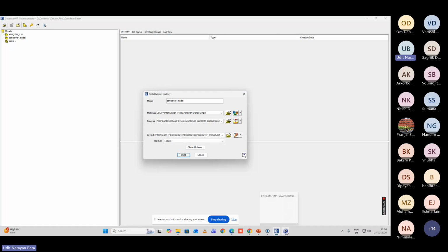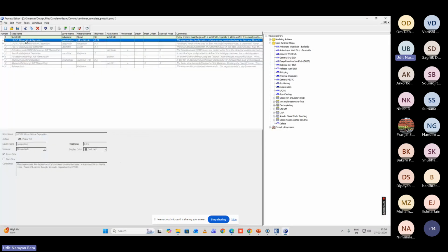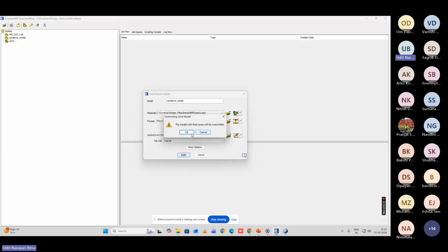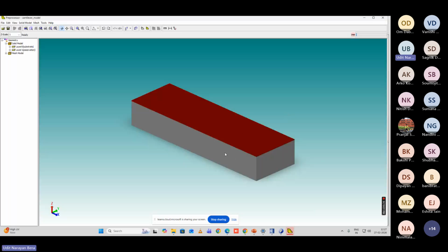Now, in the second step, what I'm going to do is add what is called a passivation layer, because we need this passivation so that there will be one electrode on top of it. So I need to passivate it from the substrate. So let's enable this, and then if you build it again, you will see another layer. You can see above the substrate there is one passivation layer I have deposited here. This is Si3N4. This is the passivation layer.